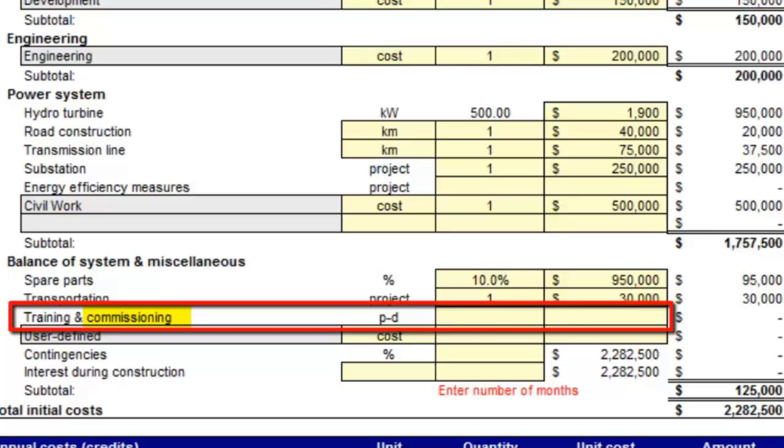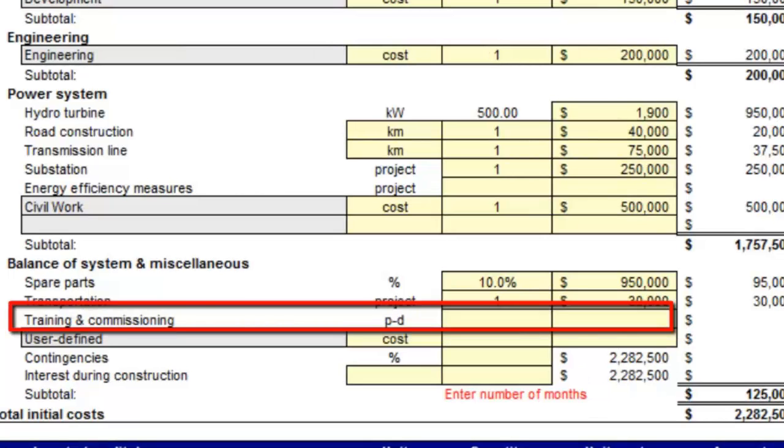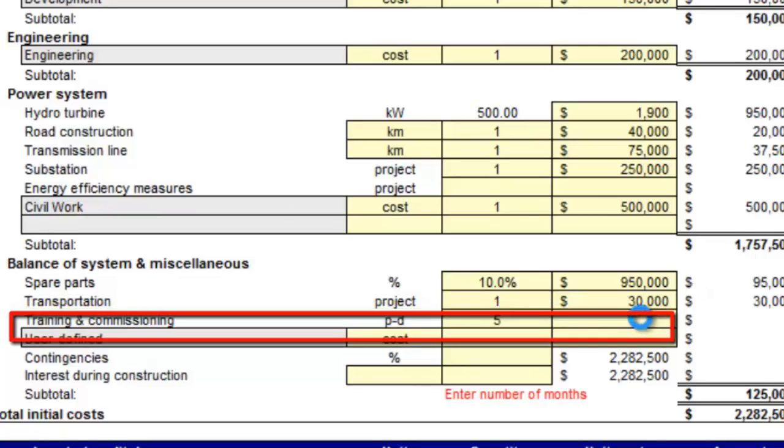Most small hydro stations have two types of operators involved, on-site and remote. Only very small hydro projects are not automated in these ways. For this project, we can expect that one operator will remotely monitor the performance of the project equipment from a computer, and one local operator close to the project area might visit the site on a daily or weekly basis for maintenance purposes. Both operators need to be trained. Commissioning involves a short testing period to ensure that everything is operating according to plan. The total for training and commissioning is therefore estimated at 5 days with $1,500 per day.